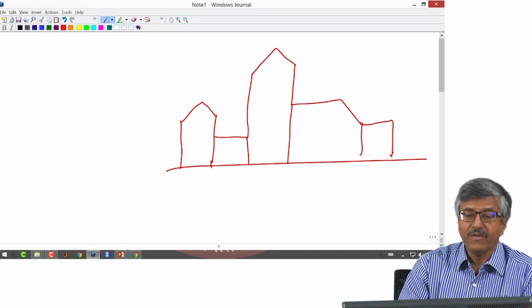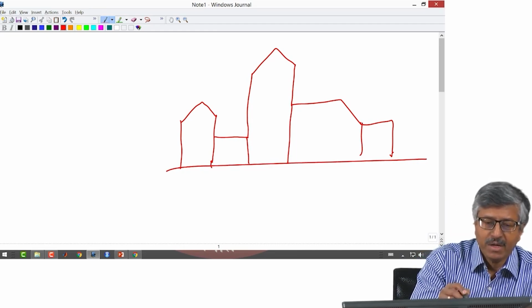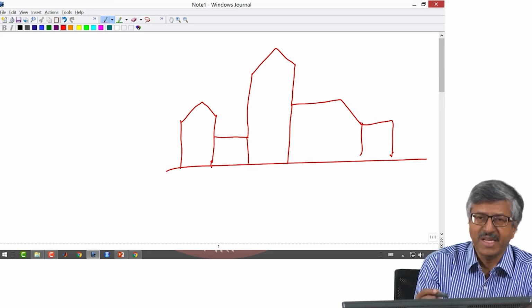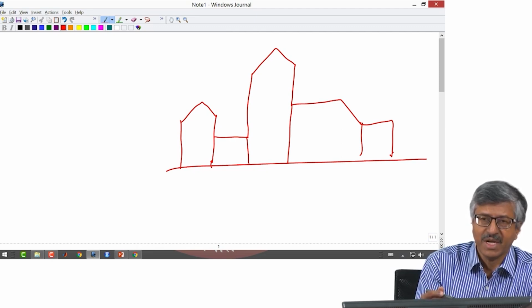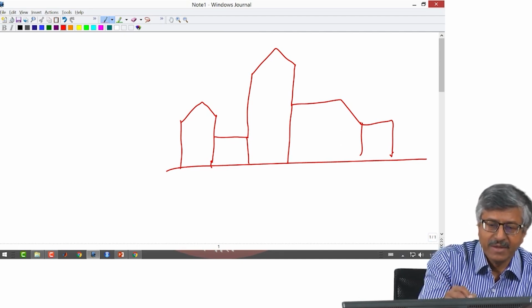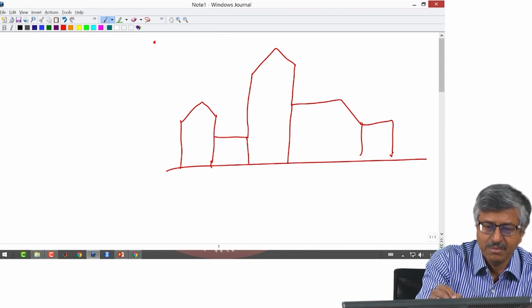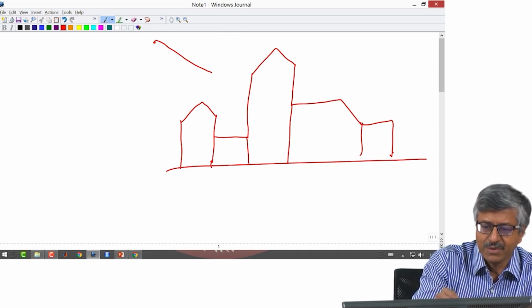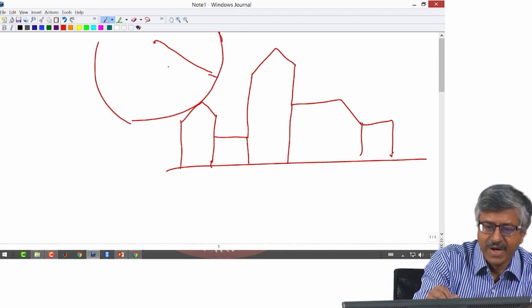Then what the rolling sphere says is that, depending upon the peak current, peak current and charge have some proportionality. It is not linear, but uses some exponential relationship. Then due to that, you know that if lightning has reached a certain distance, most likely it will strike a point at a certain distance, and you can form some sort of a sphere of radius r.